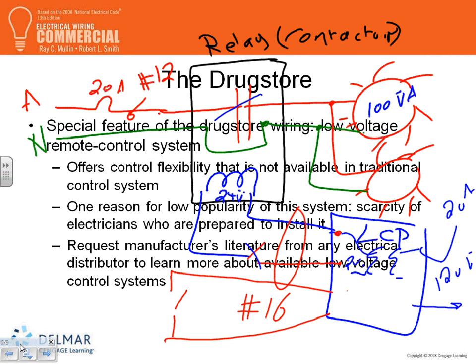Does it have its own transformer in it? Yes, you have to transform it into a 24 volt. And the emergency one, does it have its own transformer to work that switch? No, everything is powered by one transformer. Right in here. This transformer, guys, is just bringing the 120, knocking it down to 24 volts so you can power the relays and send hot to the switches. Just a time off delay or something like that? Time off delay, time on delay, depending on what you want to achieve.